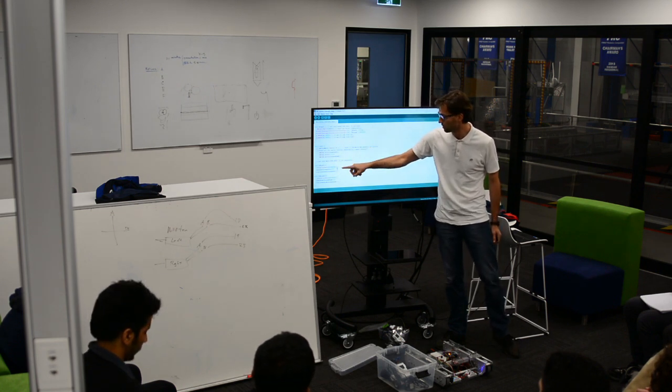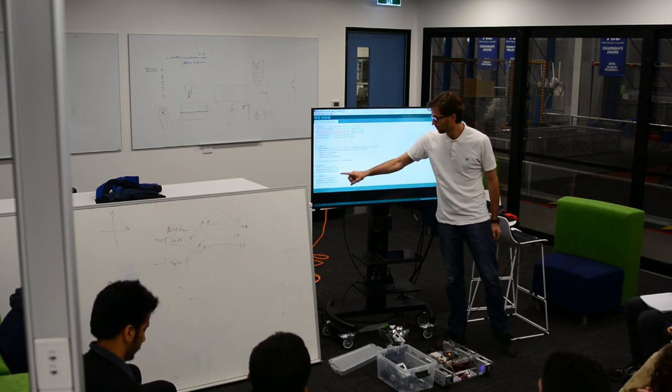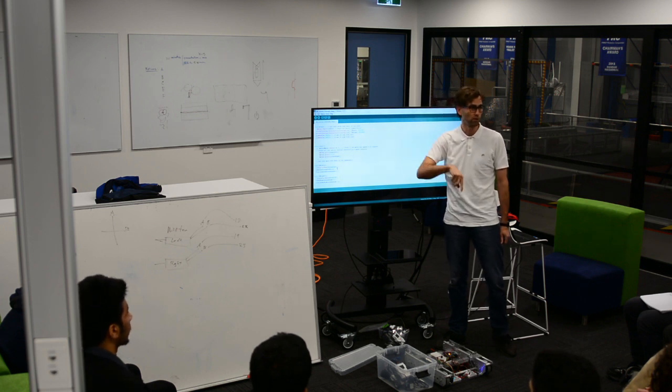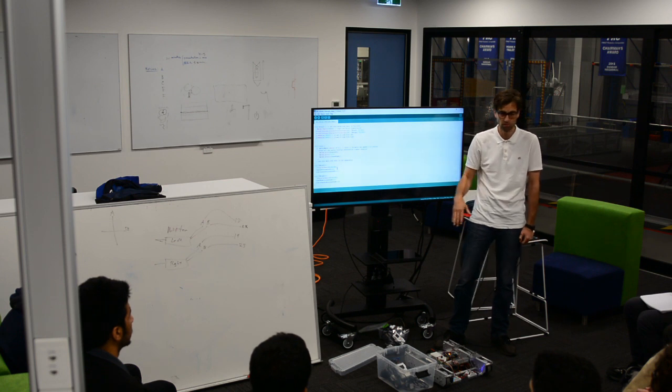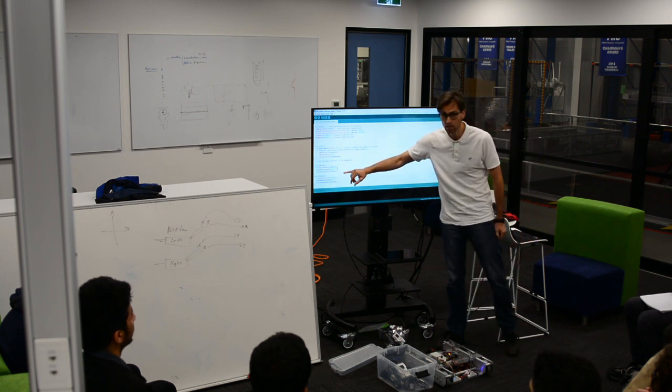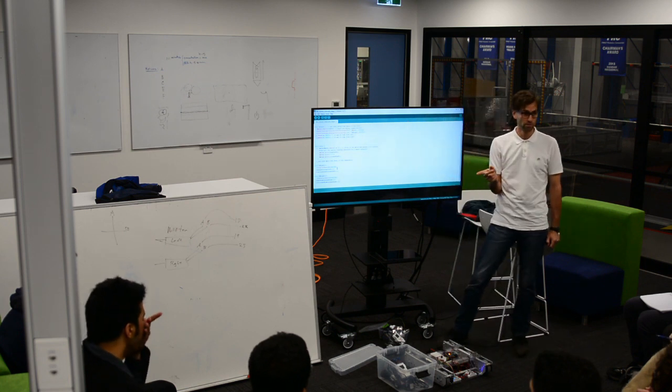So if 18 went high, we'd go in here. Then we check the state of the B channel. If B is high, we know that we went forward. If B is low, we know we went reverse. And that's how quadrature encoders and interrupts work. So that's all your interrupt service routine should do. Your interrupt service routine gets called at a high priority.